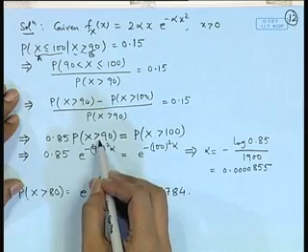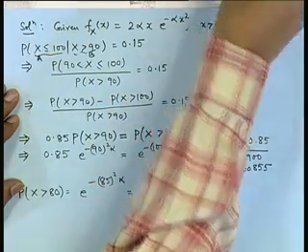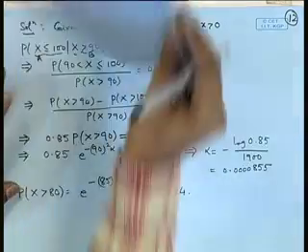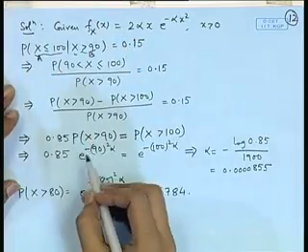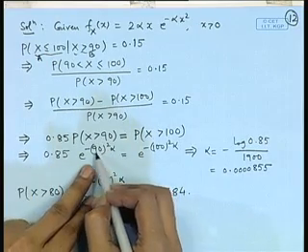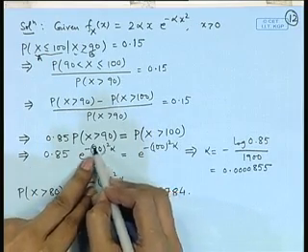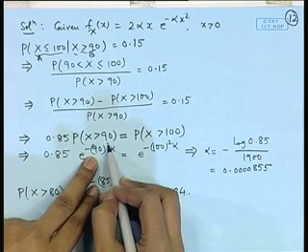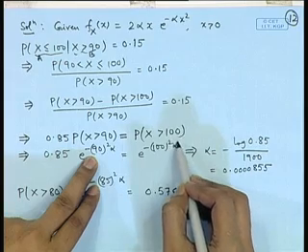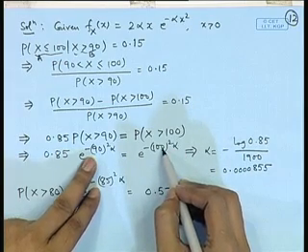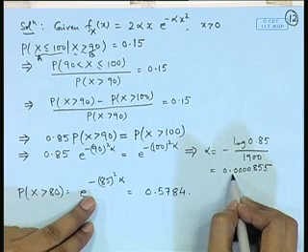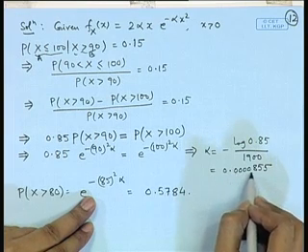Substitute the values of the reliability function of the Weibull distribution as e to the power minus alpha t to the power beta. So, if we use this, then the reliability at x greater than 90 is e to the power minus alpha t to the power beta. Beta is equal to 2 here, and here it is e to the power minus 100 square alpha, that is t is equal to 100. Now, after certain simplification, this value of alpha turns out to be quite small, 0.000855.